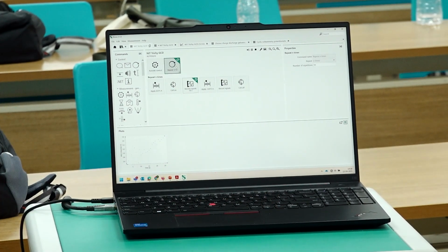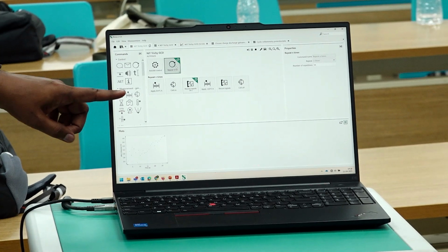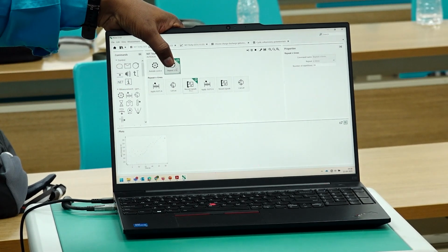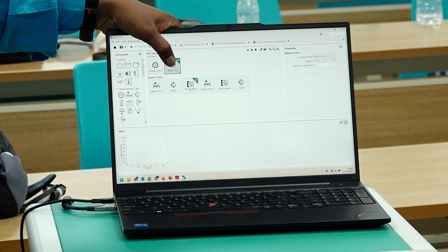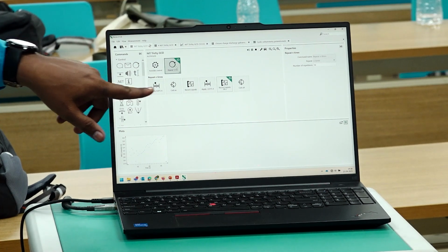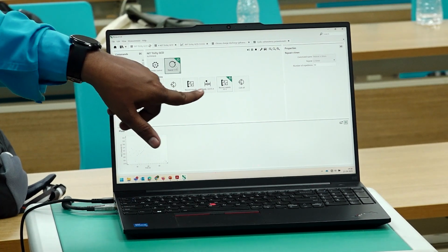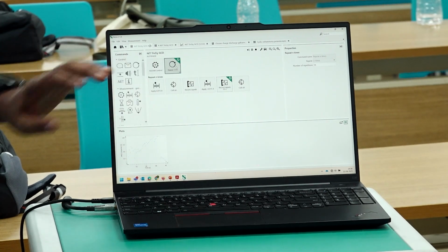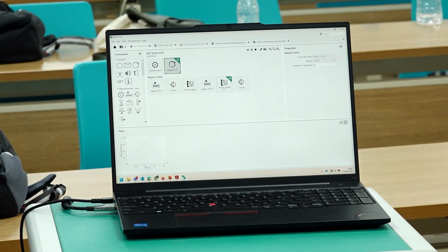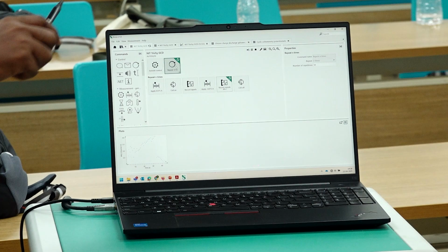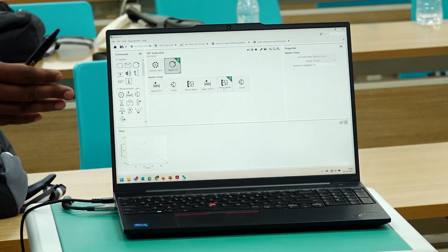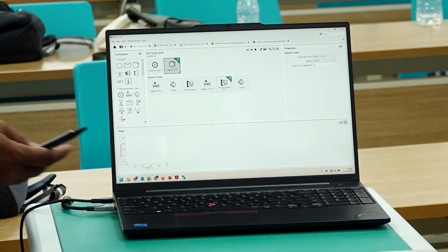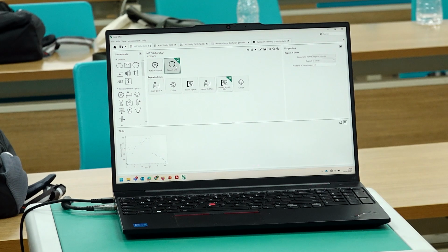In the live view, you can see how many cycles are running. Now it is showing 1 of 10, and in the sequence, the first charging is done. Now it is doing discharging, and another 90 seconds remain for discharge. Either it will discharge for 100 seconds, or if it reaches the cutoff value, it will stop and go to the next step. So you can do it in two different ways.